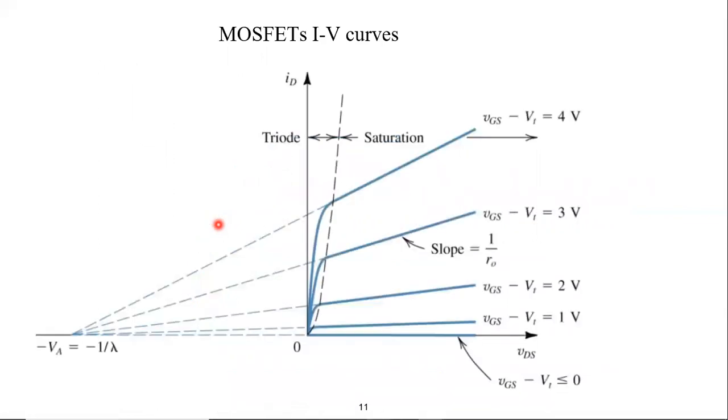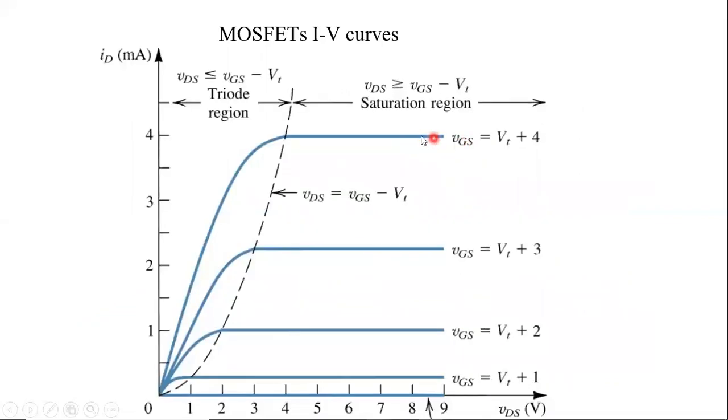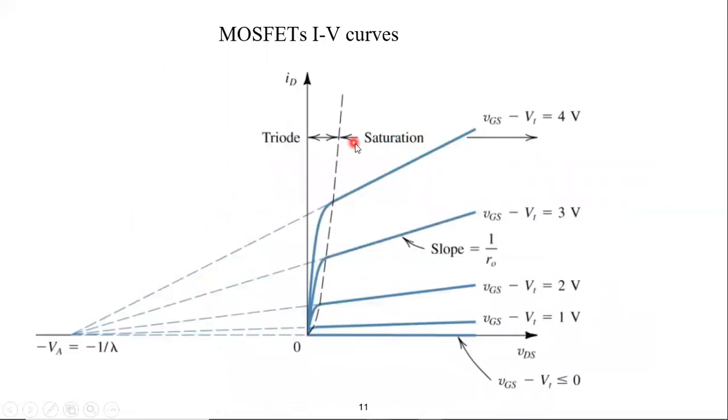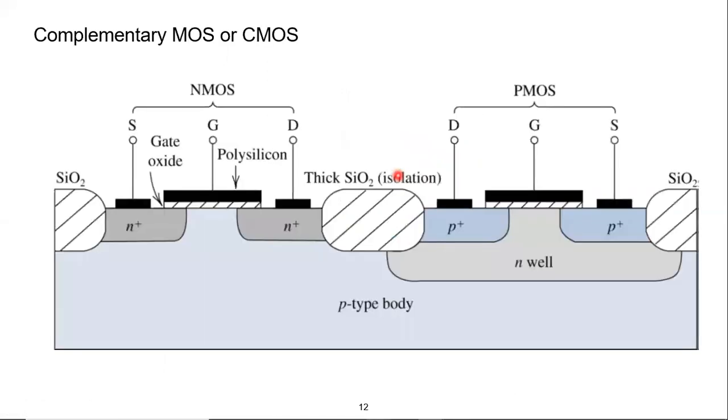There is another curve, the real IV curve, where there is an internal resistance in the saturation region due to the depletion region, as you can see here. Here the resistance is infinity, and here we have a finite value of the resistance in the saturation region, and the current is no longer saturated. Actually, it starts to increase, but with a small slope, by increasing the VDS. This was what we studied in the previous lecture. This was part 1 of our lecture.